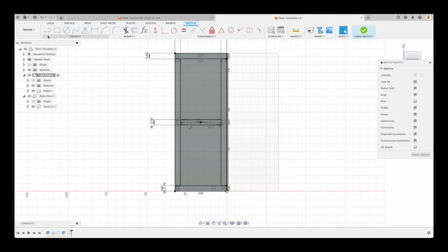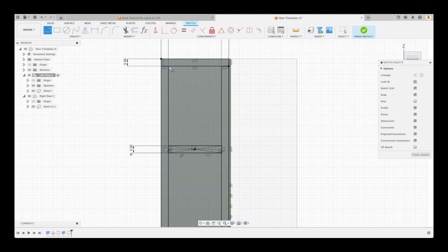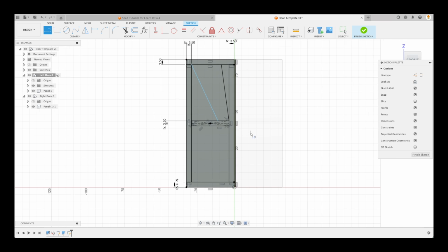But one last thing I'd like to do is create the angle pieces as well, the angle support. So I'm going to snap it to this intersection. And when I click on this edge, this line, make sure it's not snapping to anything. Okay, there we go. Now pick the corner here and do the same thing. Make sure it's not snapping to anything. I could make them parallel, but just for fun, let's practice our constraints. I'm going to make that on a completely random line.